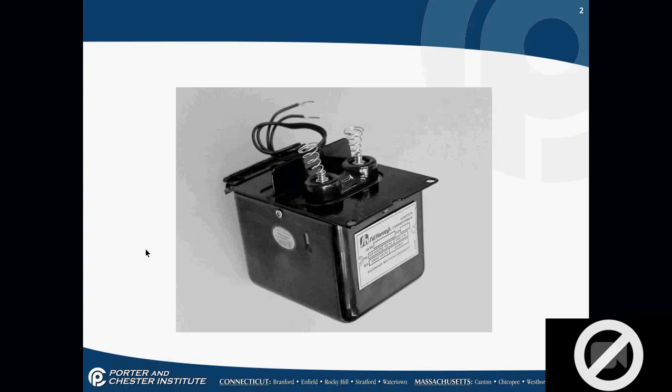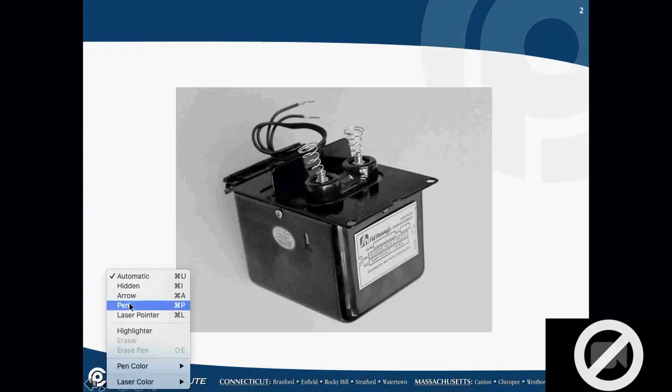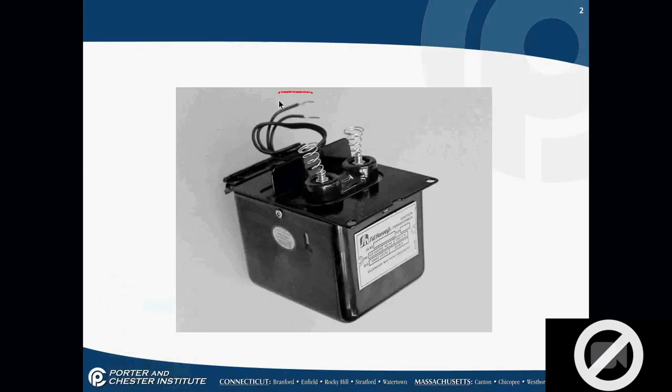Okay, this is a picture of an ignition transformer. The two leads up at the top here are what tie into neutral and our primary control, which we still have to talk about. Only two wires. Does it matter which goes to which? Not really, because we're talking AC current.